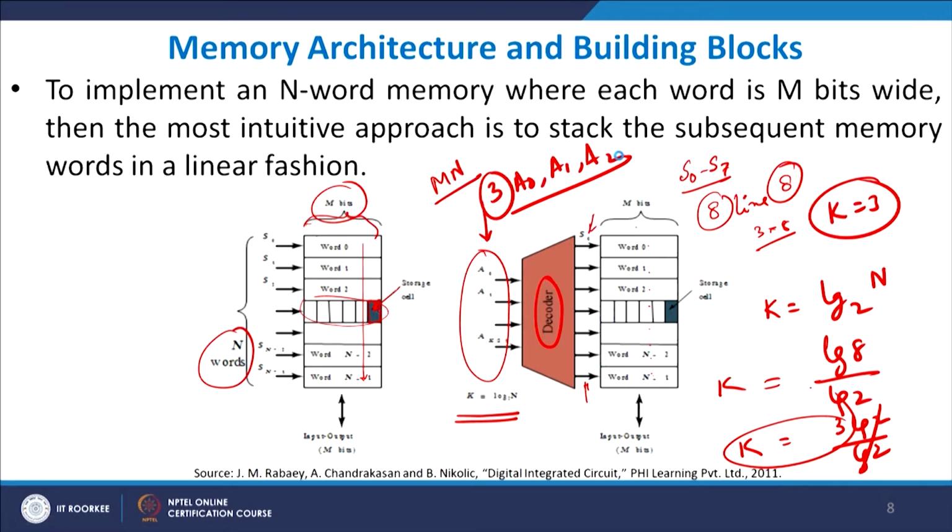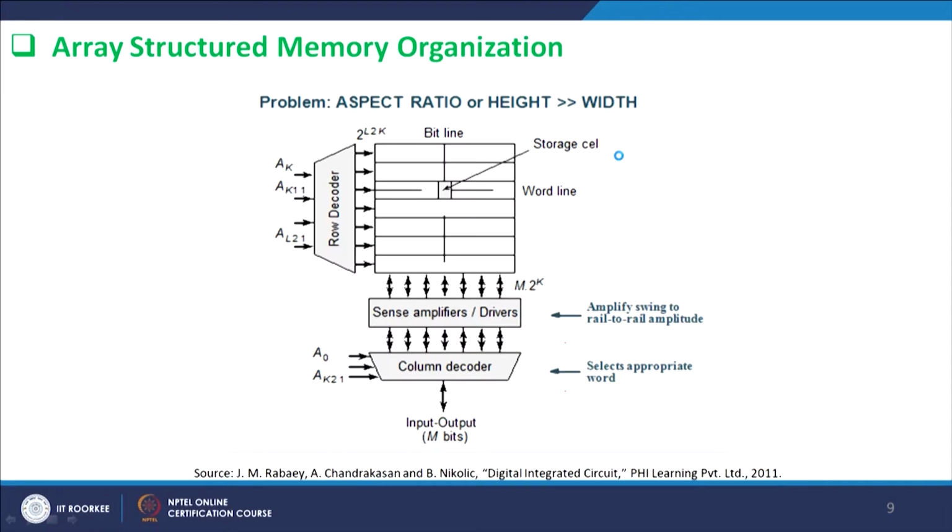So you require this into consideration. Similarly, typically you can have a row decoder, as I discussed with you, with values of A here, and you can also have column decoders, which is shown here. These column decoders will be attached with sense amplifiers. You do not have to worry what this is, but column decoders and row decoders allow you to choose a particular bit within the array structure of the memory core, right.